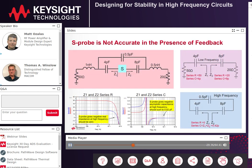As designers, we push the limits of our processes and design capabilities. As part of this, it's important for designers to be able to calculate in situ the impedances within their circuits and the resulting stability. So without perturbing your circuit, and for any given node within your circuit, you want to be able to compute the bidirectional looking impedances. Why? The bidirectional in situ impedances tell you what your load lines are for designing power amplifiers. They can tell you how well your circuit is matched at a given node. If you compute the product of the bidirectional looking reflection coefficients, you now have the classic stability index.